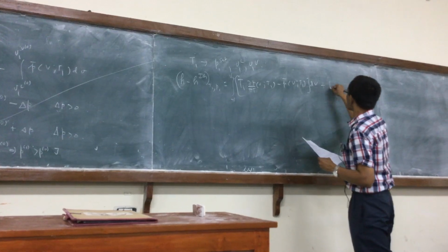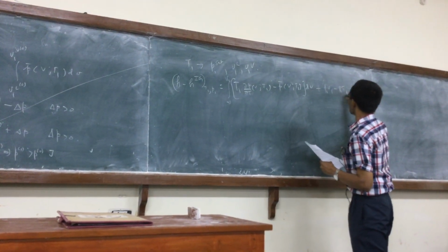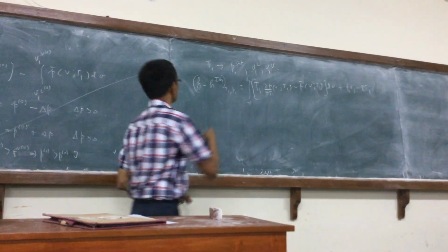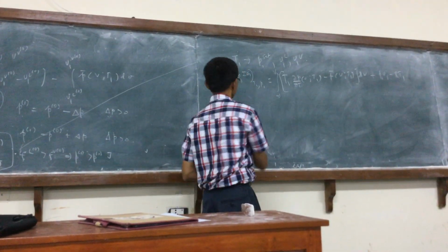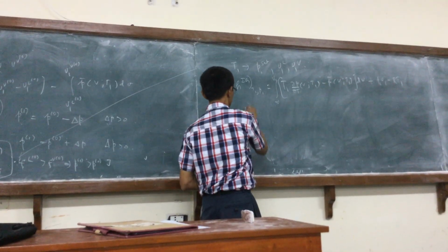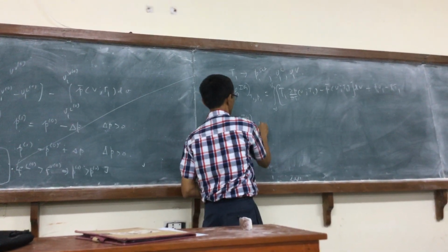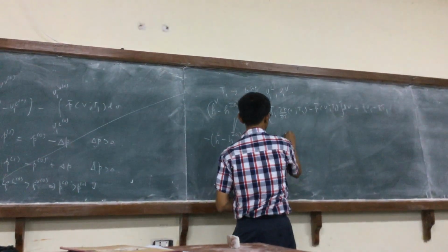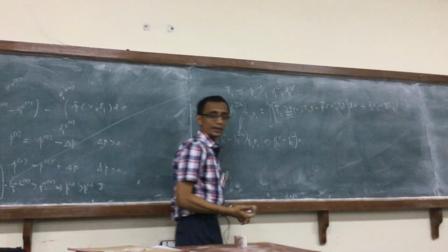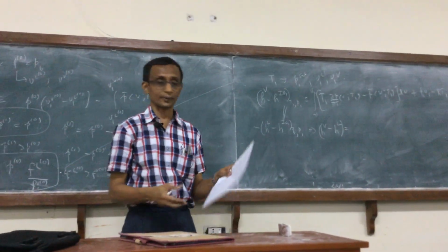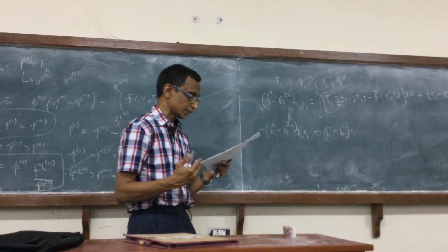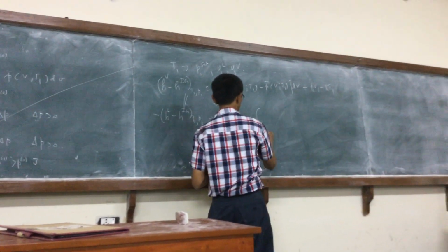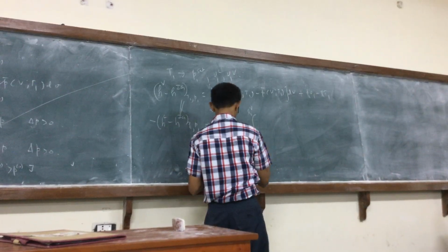V1 minus R V1. This is what I have. So if I want the enthalpy of vaporization, all I will do is I take HV and subtract HL from it. You get HV minus HL. This is the enthalpy of vaporization, the latent heat as it is called, a very important quantity associated with liquid vapor transition. So this can be easily written as V1L to V1V.